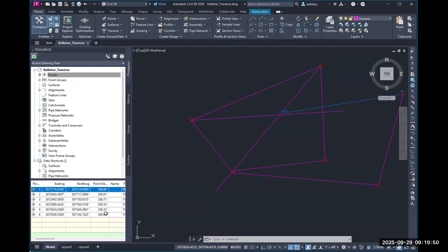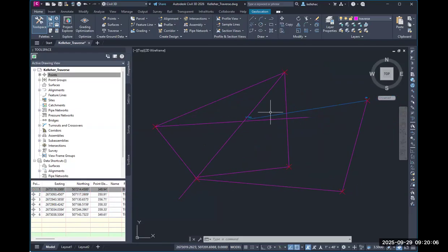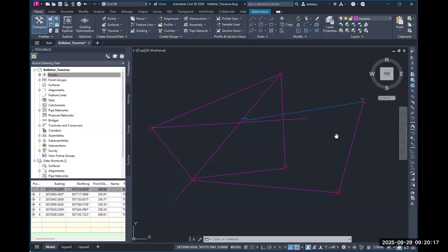So you are going to want to enter these points into Excel to bring into your report. So you now have coordinates, you have all of the information that you need to report error for your linear misclosure and your distance from the Colton Chapel Spire. You are going to make this into a nice map. I would ask one member of your group to focus on that. At this point, you are going to turn in your traverse drawing.